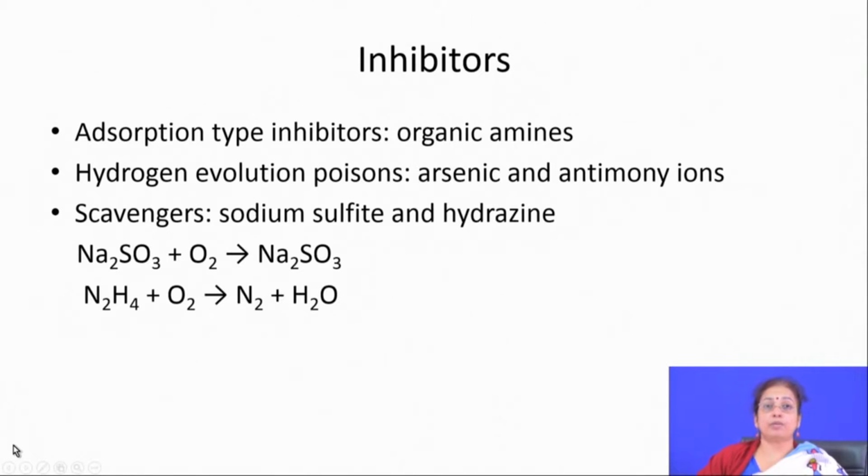If you talk about altering the environment, as I mentioned, you can reduce the temperature, you can reduce the velocity, but sometimes these are not in your hands. So, you cannot really play with them, because those are natural things, and that is where you have to use your component. So, in that case you can apply inhibitors to reduce the aggressiveness of the media, the aggressiveness of the particular environment.